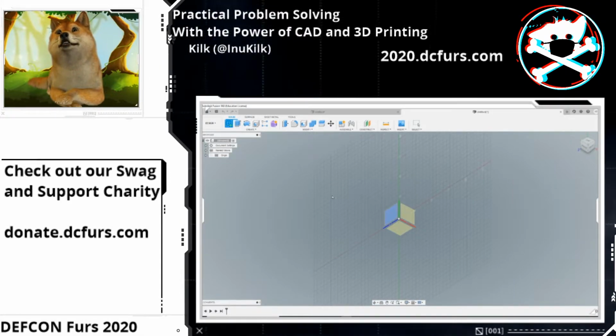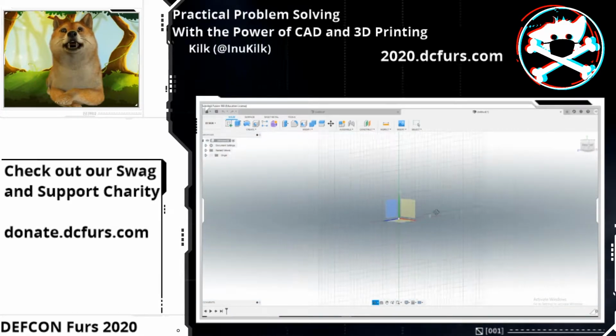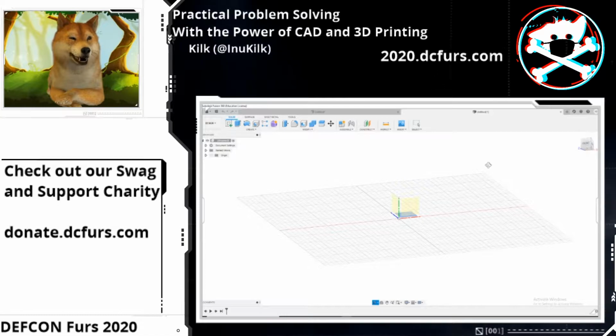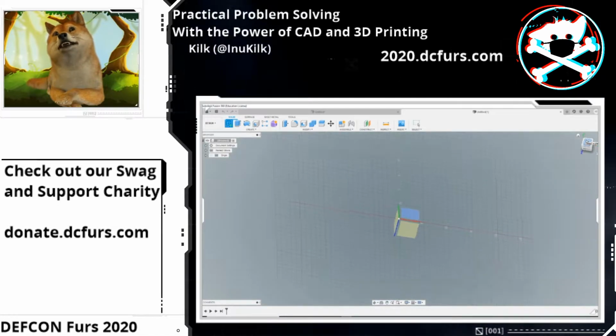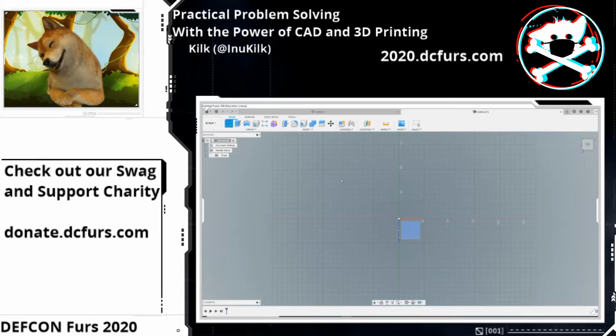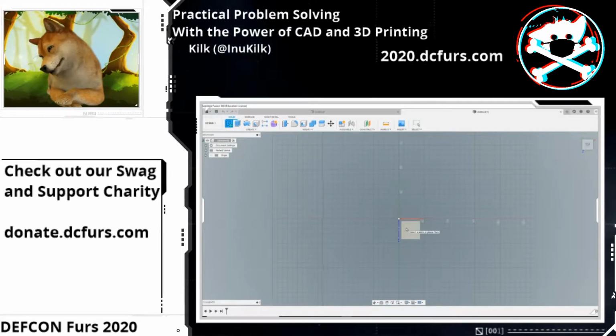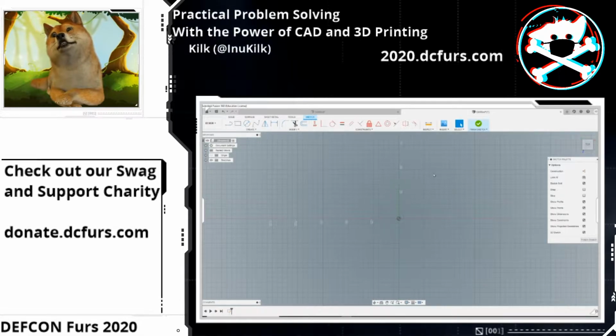Depending on what you're building, you could build it from the front, from the right, from the back, left, and bottom. It's all over these faces. But for today's purpose, we're going to start from the top view. So once you hit the top view right here, it should look like this. You want to click the top here. So now we are sketching on the top view, and your menu should look like this. Now you have this sketch palette here.